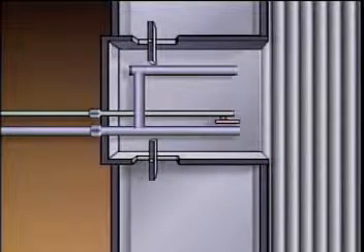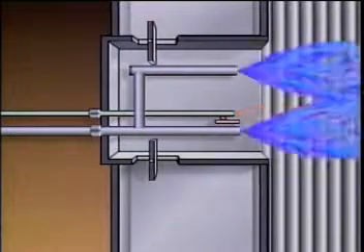In a typical natural gas burner, the gas is fed under pressure from the gas supply to a burner manifold. From the manifold, the gas flows into pipes called gas spuds. Holes in the ends of the spuds direct the gas into the boiler furnace.